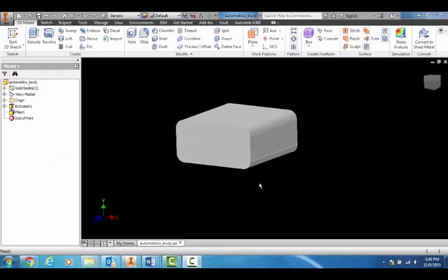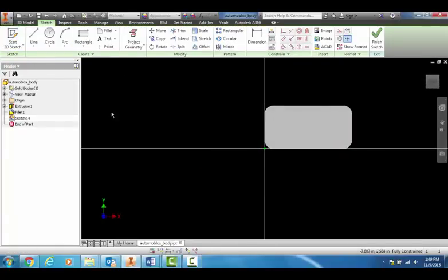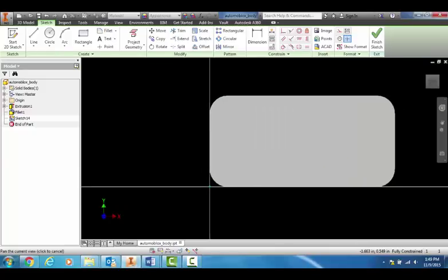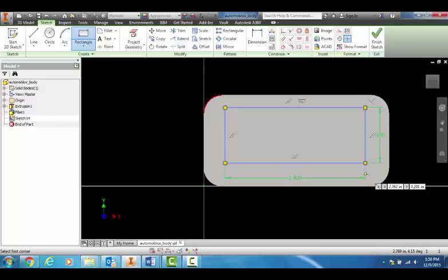All right, so let's start making this hollow piece here. Let's click on this face, or plane, and click on Start 2D Sketch. Let's zoom in here. Let's click on our rectangle tool. Draw a basic rectangle, and if you remember from the sheet, it had a length of 2.4. Hit the tab button, and a height of 0.93, enter.